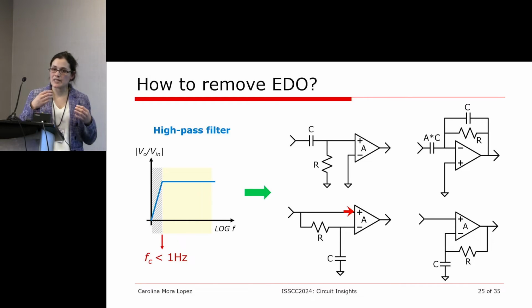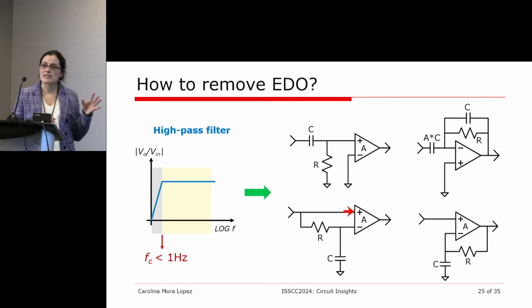For example, if this electrode offset gets very large, or gets negative or positive, then your amplifier needs to be able to deal with that offset without going out of the linear region, without saturation, or without affecting the differential pair. And this is not always evident, especially because electrode DC offsets cannot always be predicted very well. They can change over time depending on the conditions, on the temperature, or because of the degradation of the materials. So you cannot guarantee that your amplifier will always work if you apply the electrode DC offset directly.